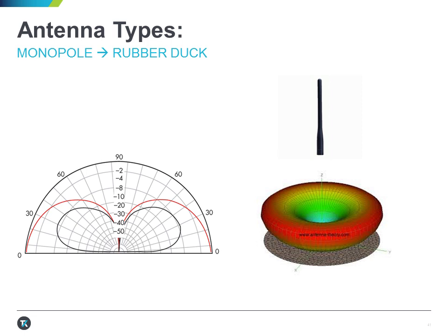of energy. While this might not sound logical, what we're really doing is exploiting the sensitivity of the spectrum analyzer. Remember, as we get closer to the source, the amplitude of the interference is going to increase. As we start adding attenuation, we'll be attenuating the clutter or the adjacent channel spectrum around us. And as you get closer physically to the emitter, we will be able to see it with our spectrum analyzer because our spectrum analyzer is very, very sensitive, even with all of that attenuation on the input.